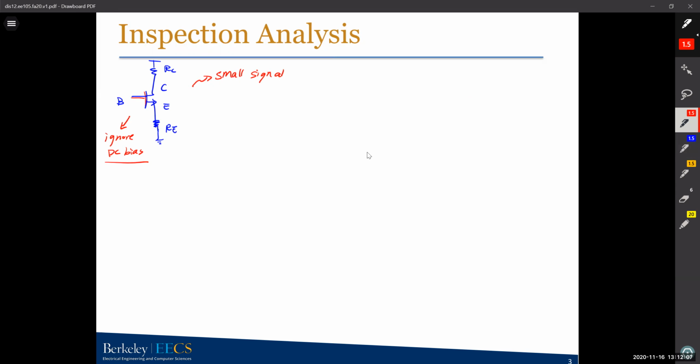I just put a single transistor here, and I want to draw the small signal model of it. The small signal model would just be, I'll have a Vs as an AC voltage source, and I have my Rs as an input signal resistance, and I have my RB, which is usually the biasing circuit, so it's R1 in parallel to R2, and also the BJT.